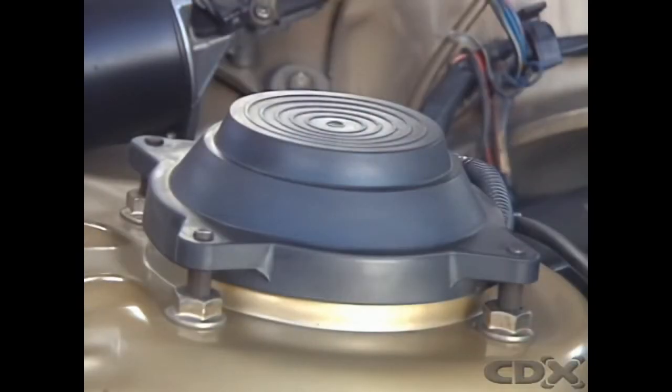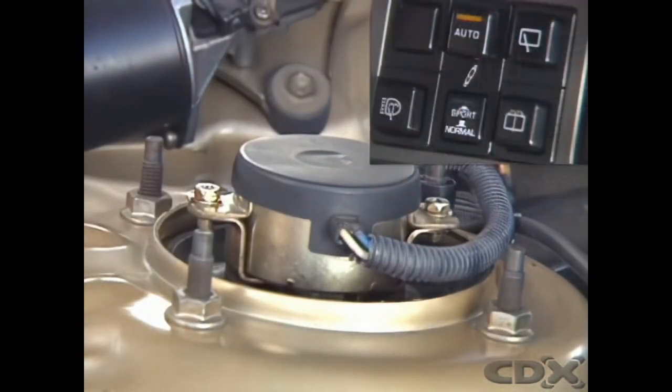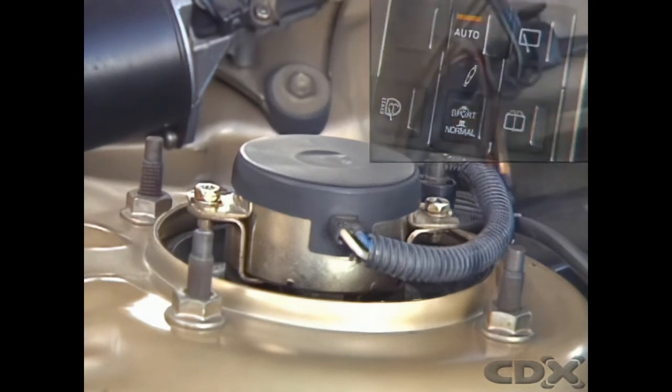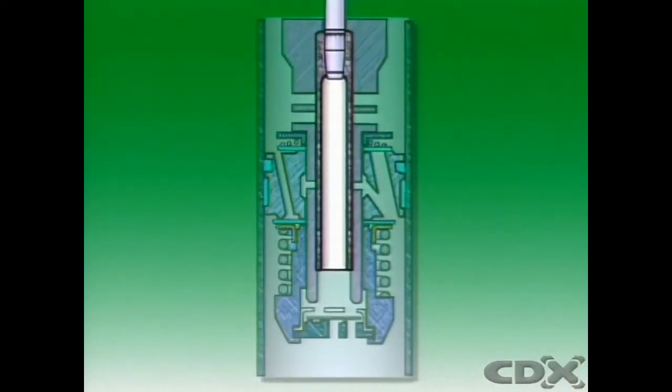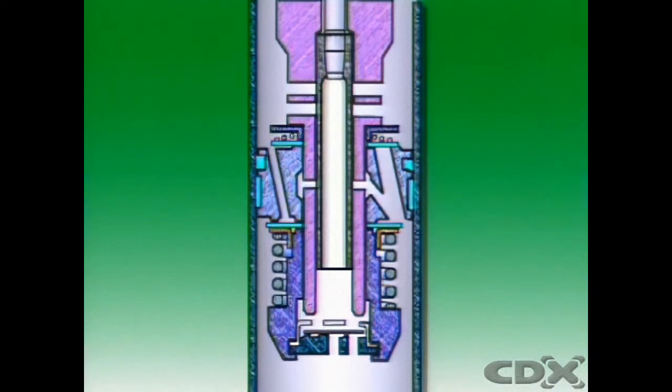Adjustable rate shock absorbers provide a means of changing their rate of dampening of the spring oscillations to suit road conditions. Electronic controls let the changes occur either automatically or as the driver prefers. Each shock absorber has a rotary solenoid that can alter the dampening rate by changing the number of restrictions the oil must pass through.